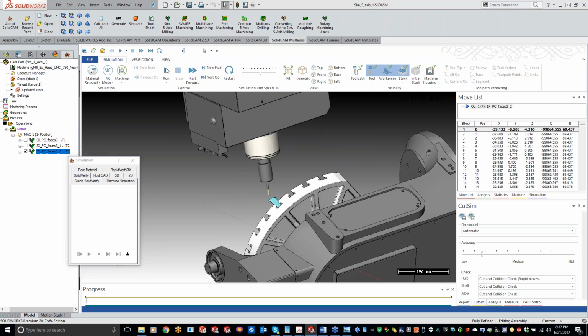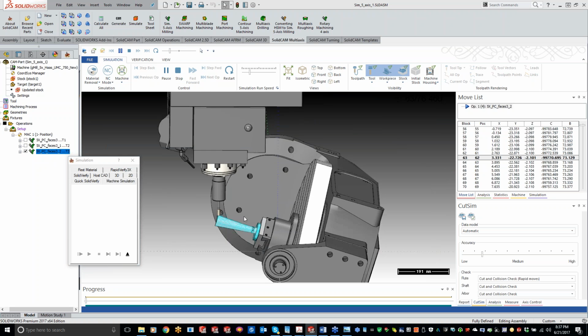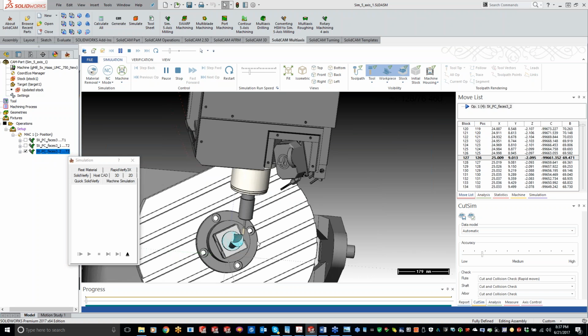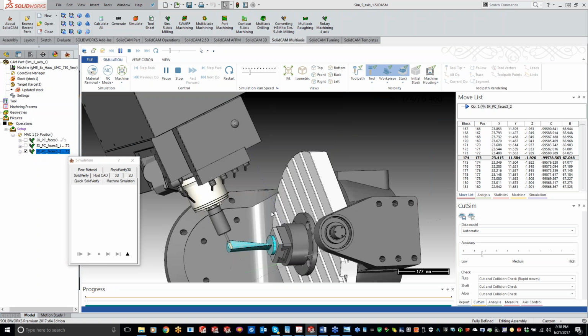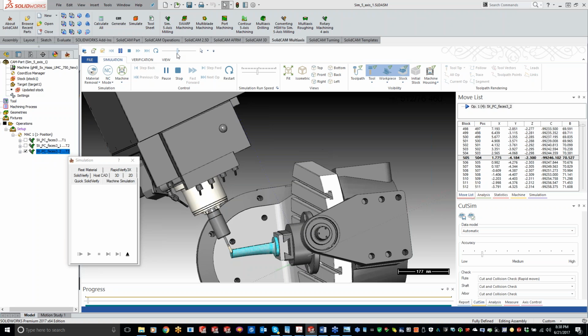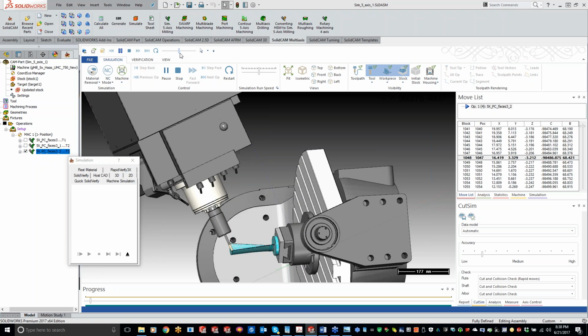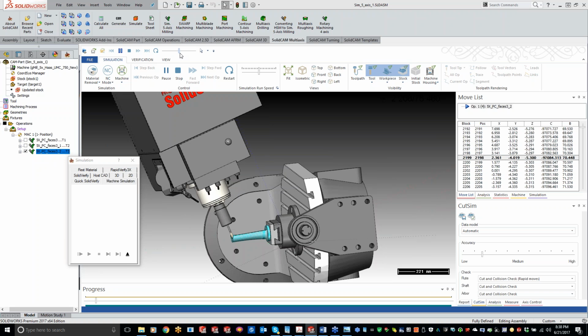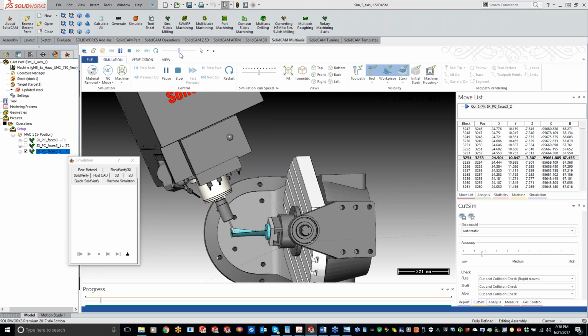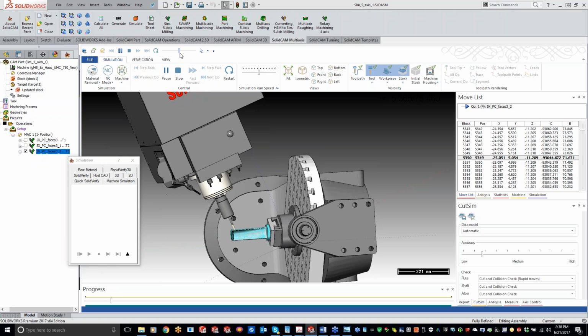I'm going to run a little slow here, so you can see we're kicked up at that 20 degrees, and also working on 20 degrees of the side of the cutter here. So you can kind of see everything. Let me speed it up just a little bit for you. You can really see that trunnion doing a lot of work right there, and you guys are going to get a real nice finish. Since we're using that side of the cutter, kicked over that leg of 20 degrees and side tilt of 20 degrees, you guys have a ton of control in here.